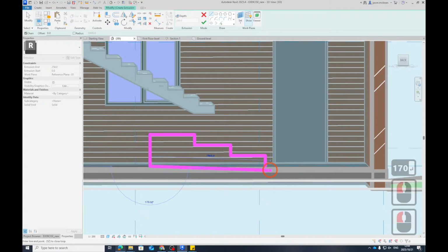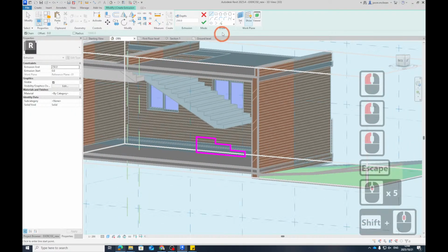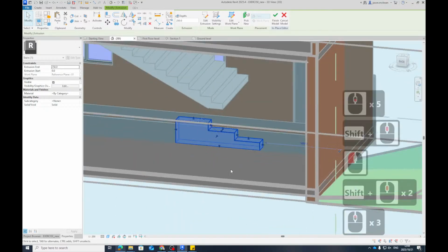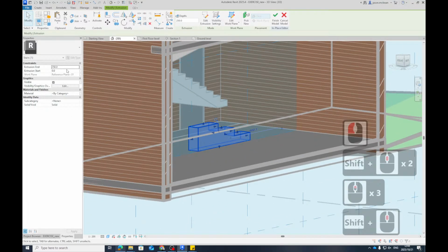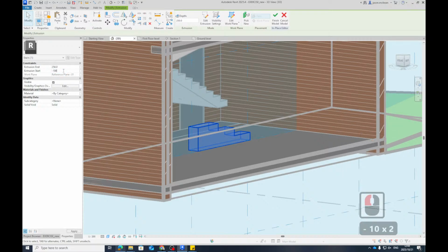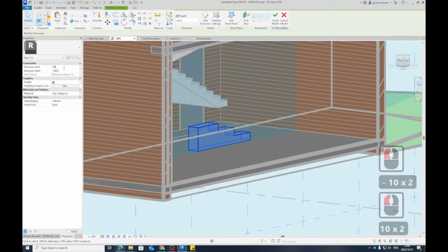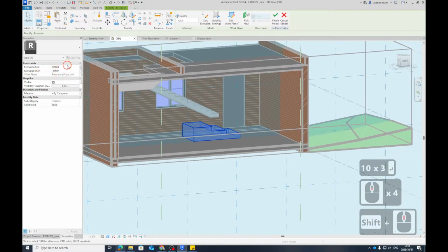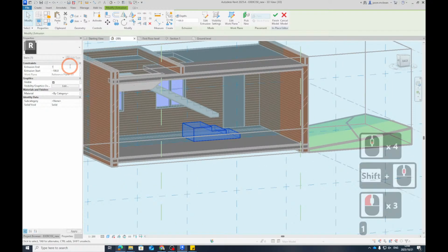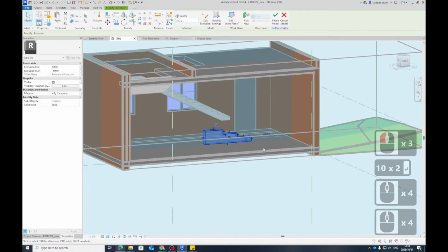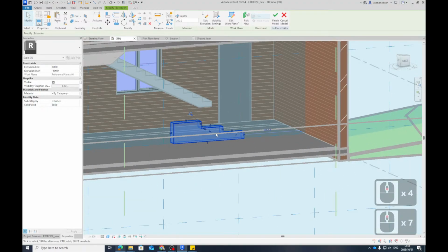It's where Revit wants to work from, but I'll show you now in 3D. So when I finish this extrusion, the work plane, it needs something to work with. Yeah. And you see the start and end extrusion. If I made that minus 100 and I made this 100, it's always trying to work around. Okay. It always needs a work plane. By default, your levels are work planes. But you can use grids and you can use reference planes.